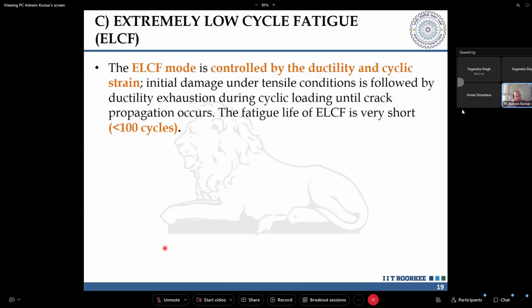So among all these concepts, there is ultra low cycle fatigue, which corresponds to earthquakes. There is high cycle fatigue, which corresponds to bridge decks. All these are under cyclic load itself, but the number of loads differ starkly, because in the bridge deck, the stresses developed are in the elastic range itself. Here it is totally in the nonlinear range. But the commonality between both fatigue types is the definition that we started off with: there is a crack initiation stage, a crack growth stage, a crack propagation, and final fracture. That is common in the fatigue damage that we see, whether it is ultra low cycle or high cycle fatigue, right?